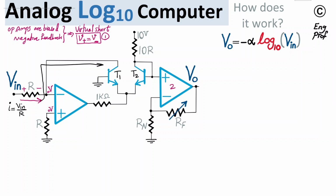Alright, with that in mind, IC1, which is the collector current of transistor 1, is now equal to I, and as you can see is equal to Vin over R. So I'm going to write it here: IC1 is equal to I, equal to Vin over R. Let's name that as equation number 2.